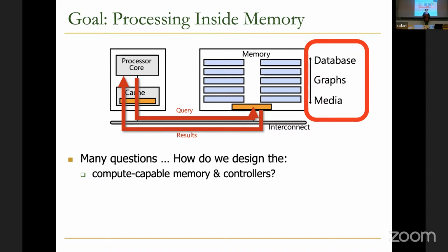These memory controllers, for example, can help on deciding when to offload something to memory or when to not offload something to memory because maybe the data is in the cache. Or maybe because you will bring the data from memory to the processor and then you're going to reuse it a lot. In those cases, probably it also doesn't make sense to offload the computation to the memory, right? Because the processor is faster than any sort of processor that we can have in the memory side.